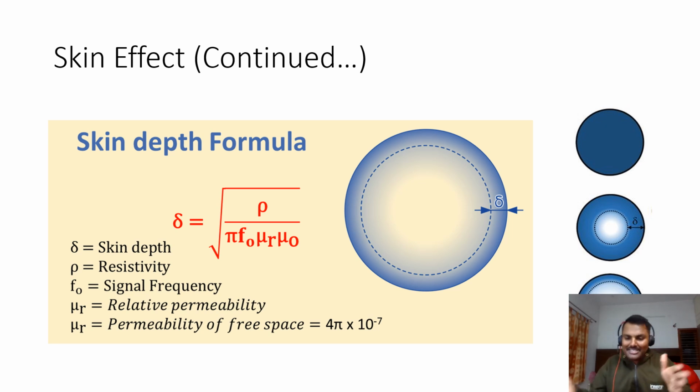How the equation is derived is out of scope for this topic, but skin depth is the distance from the wire's cross sectional edge inward. If frequency increases, the depth decreases, so current flows only at the edge. If frequency decreases, the depth increases, so the current flow depth also increases.